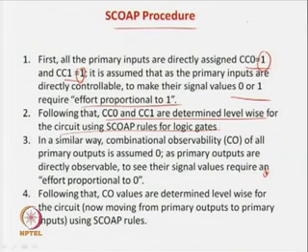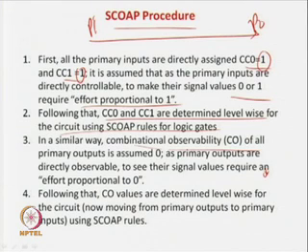Then you go for the next level of the gates, then you have to apply some rules that we will study in a similar way. So, you have to go to the similar rule, and if you apply it, then we can go from the primary inputs to the primary outputs, and every net will have the value of CC0 and CC1. Similarly, we have to go for combinational observability. Combinational controllability goes from primary inputs to primary outputs, this is the level of propagation.